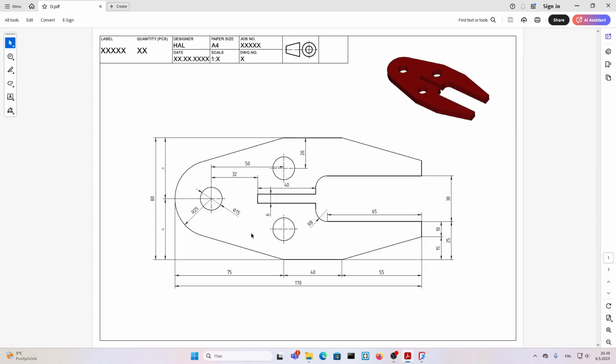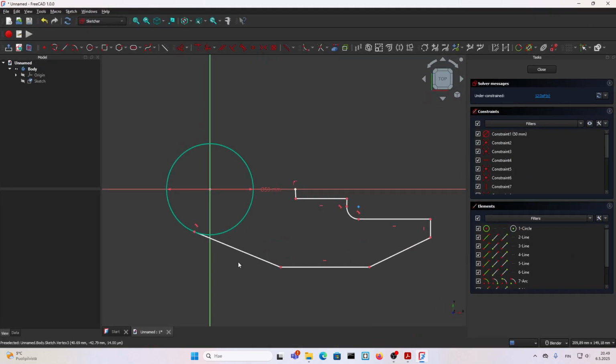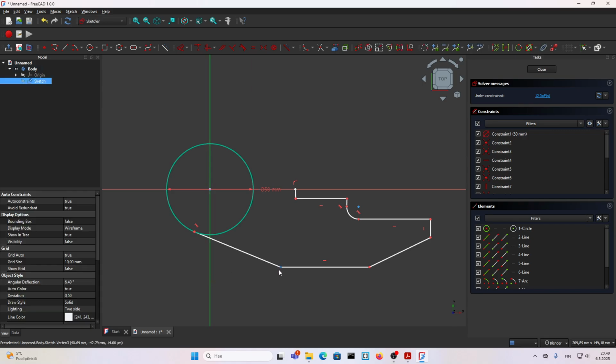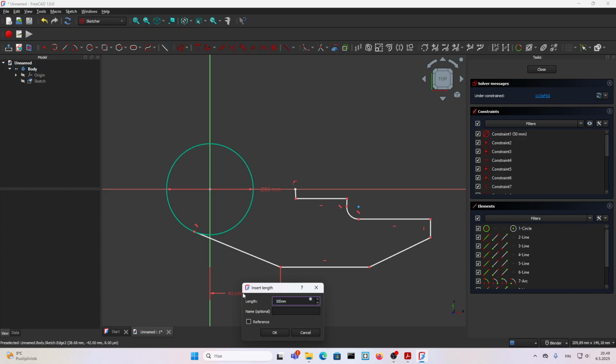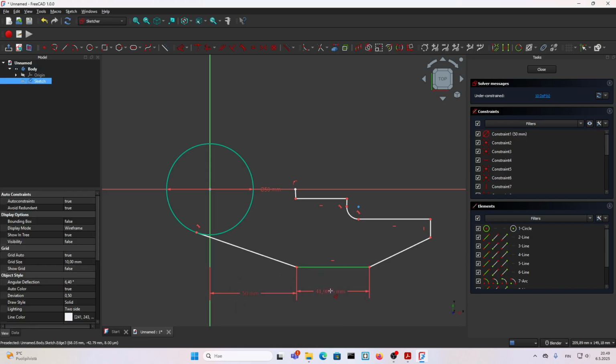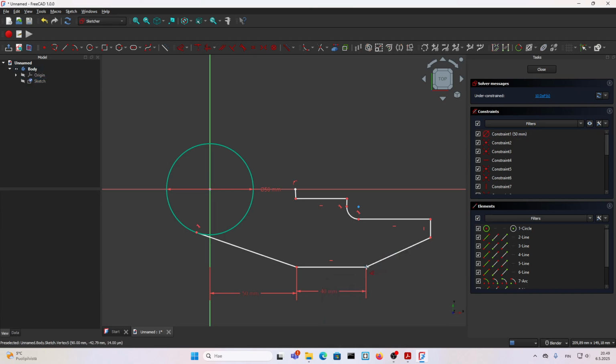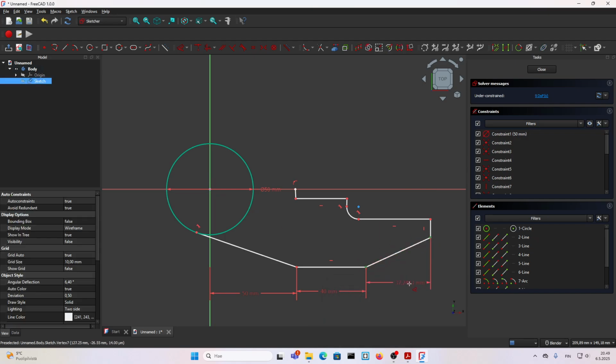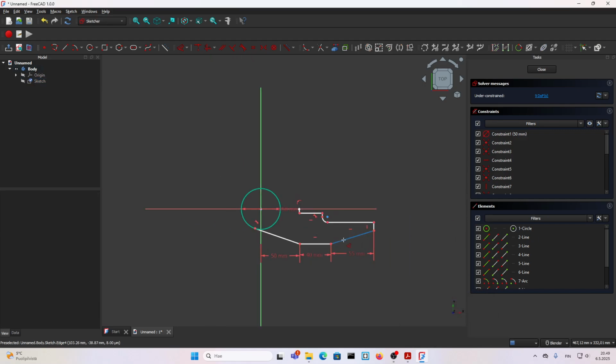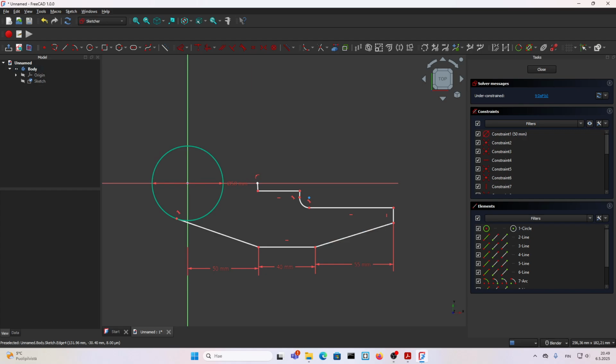From the drawing, I can see that this is 75. Our coordinate is in here. The radius of this is 25, so if I go 25 to here, it means that this is 50. 50, 40, 55. Okay. D from the keyboard, 50. This was 40. And from here to this dot was 55. And we are here. Right click, exit the tool.